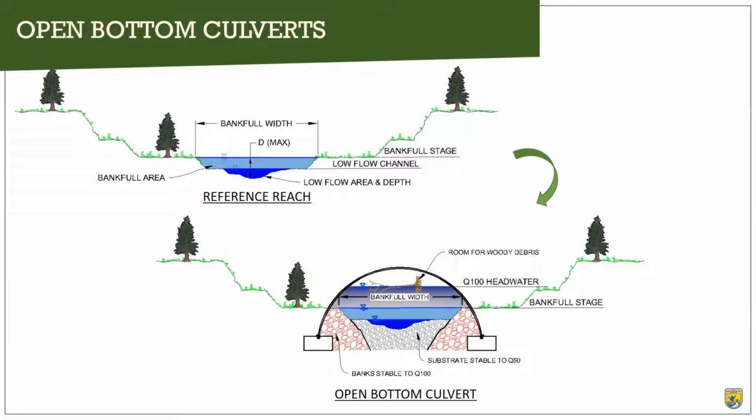And open bottom culverts are another option. And they're a great option because they do allow for some groundwater connectivity, but we have to make sure that we protect those footings in an open bottom culvert as they're more susceptible to scour.